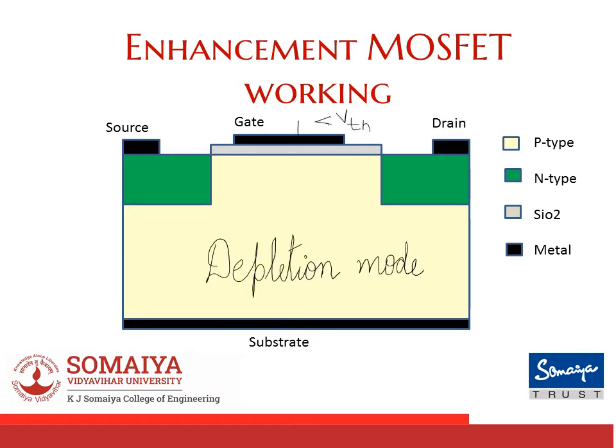Let's see what happens when you apply a gate voltage which is very close to 0 volts or a little less than VTH. When that happens, you don't have any free charge carriers building up in the channel. The channel in this case is going to be occupied by immobile ions, and hence this mode is going to be called depletion mode, and there will be no current flow in this case. So your enhancement mode MOSFET will only conduct when it has a positive voltage applied, in case of an NMOS. For all other voltages, it will not conduct.